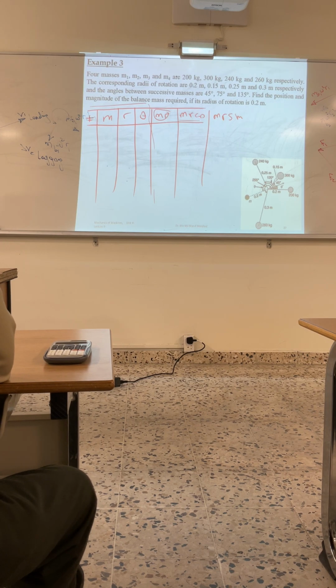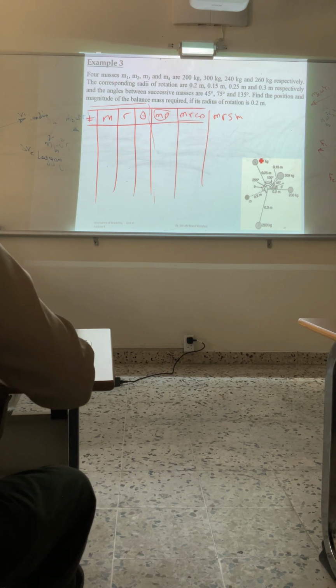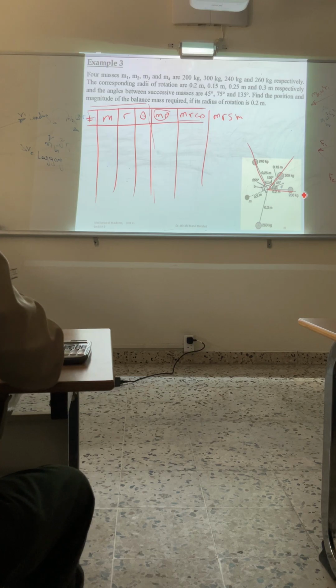You have multi masses. Okay, can someone turn on the light there? So you may have multiple masses causing the multiple unbalance, but at the end you should be able to figure out the resultant of this unbalance, and it will be somewhere here, and then you add the balancing mass in the opposite direction. Clear, guys? Same concept. Exactly. So now, let's do the business.